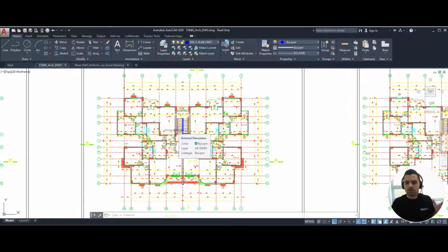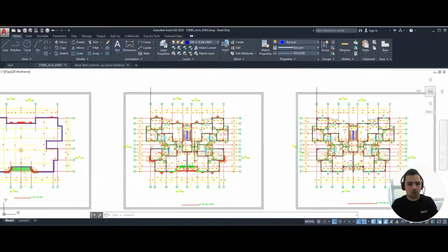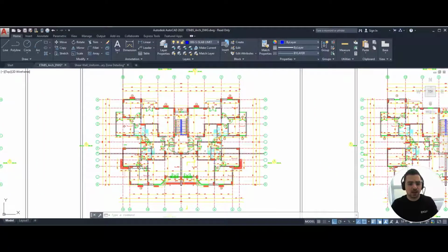Of course, the first thing is we do not need to interfere with the architectural design. So we cannot place a shear wall in the middle of a living room, for example. Now, usually we place shear walls along the outer periphery of our system. Now, why is that? This is to give a big lever arm for our structural system as a whole. A lever arm is basically the distance between two forces, which are your compression and your tension.